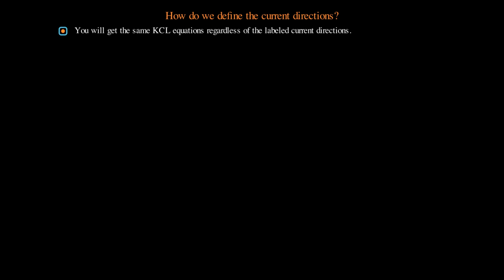Let's move on to the second question. How do we define the current directions? The short answer is that it does not really matter how you label the current directions, because as mentioned earlier, you will get the same KCL equations regardless of the labeled current directions.